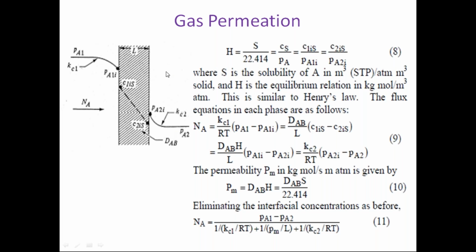So you can use one sweep phase, so that it will take all the molecules which have permeated through the membrane and reached the other side, and carry them away. That phase is inert, but in the inert phase you will find a very dilute presence of the component which does not have much permeability through the membrane, while the component which has access to permeation will be present in very high amounts, so that the concentrations on this side compared to that side will be different. Therefore Kc1 will be different from Kc2.